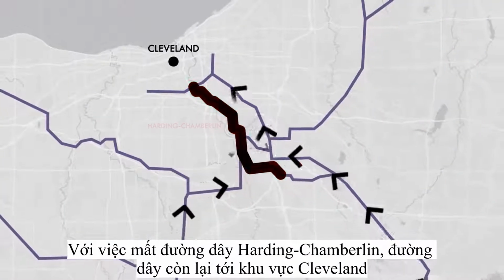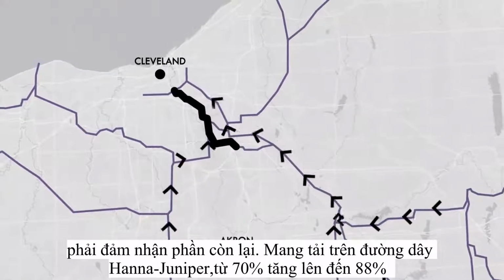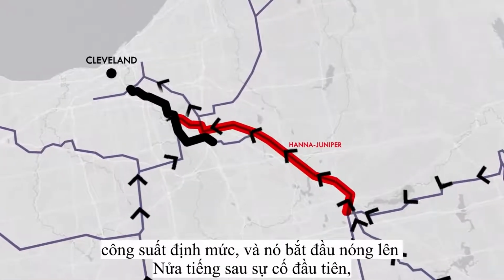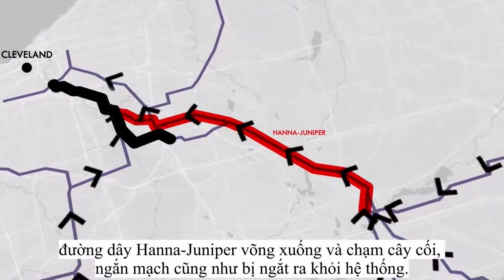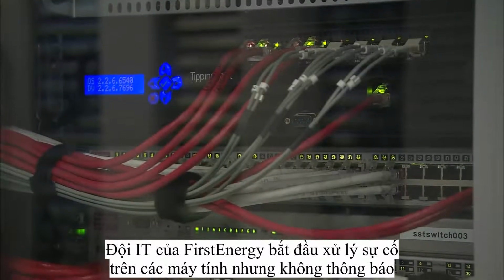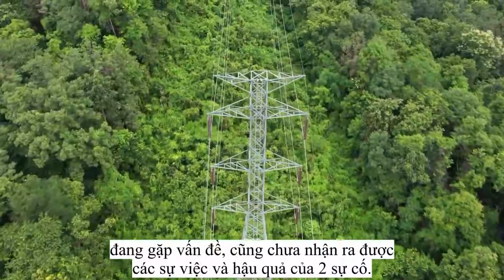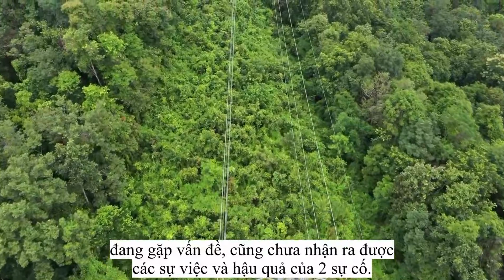With the loss of Harding-Chamberlain, the remaining transmission lines into the Cleveland area took up the slack. The current on one line, the Hannah-Juniper, jumped from around 70% up to 88% of its rated capacity, and it was heating up. About half an hour after the first fault, the Hannah-Juniper line sagged into a tree, short-circuited, and tripped offline as well. The First Energy IT staff were troubleshooting the computer issues, but still hadn't notified the control room operators. The staff at MISO, the reliability coordinator, with their state estimator issues, were also behind on realizing the occurrence and consequences of these outages.